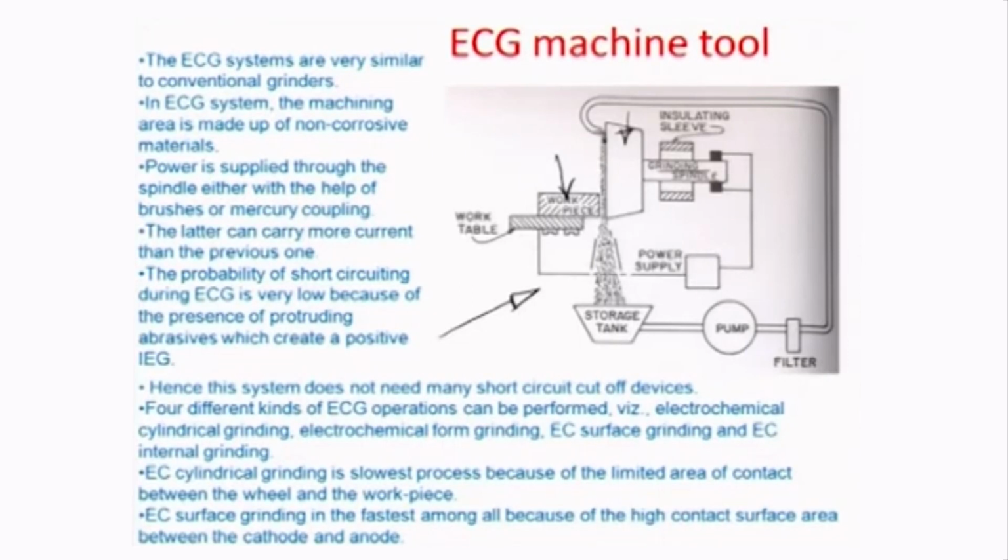So, you are flowing the electrolyte very close to this wheel, and the wheel starts working on the workpiece surface, by positioning relatively with respect to a high precision work table. Whatever material comes out as debris or gases in the electrolyte is stored here in the tank, which is again reused by a set of filtration techniques and pumping techniques. And there is of course a power supply between the workpiece and the grinding tool to ensure the electrochemical transport. So, by and large, the following things need to be taken care of for designing such a system.